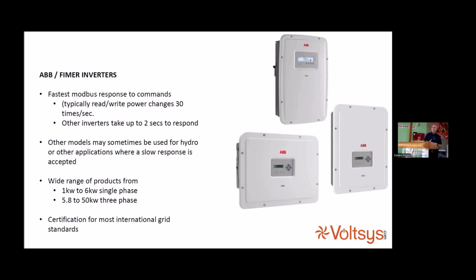It used to be 10 times a second for the wind inverters. But we find it very hard, so we're interested in looking for an inverter manufacturer who can offer that kind of speed, because most of the Chinese inverters, and the German ones like SMA and Fronius, the Modbus response is about 2 seconds, which is too slow for this kind of wind turbine. So if anybody knows of an inverter in that segment that has a very fast Modbus response, we're always looking for that.